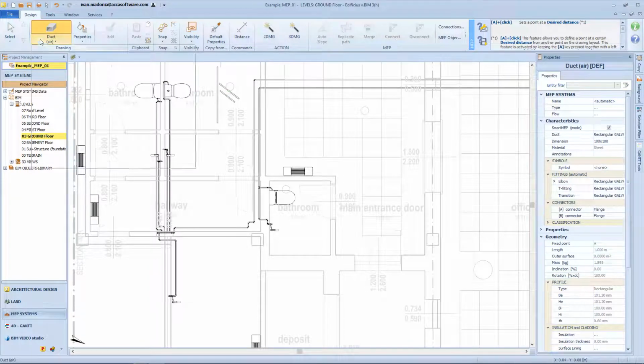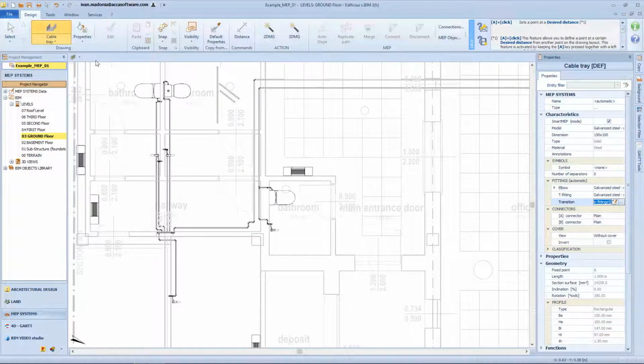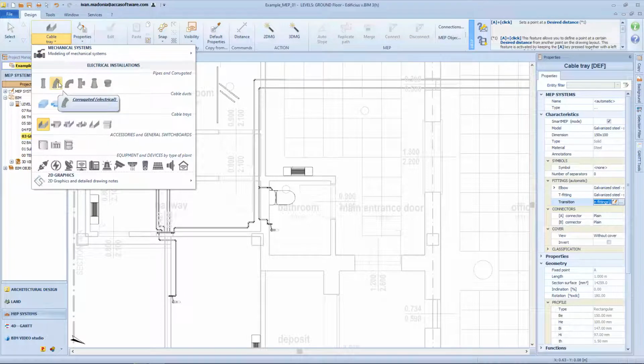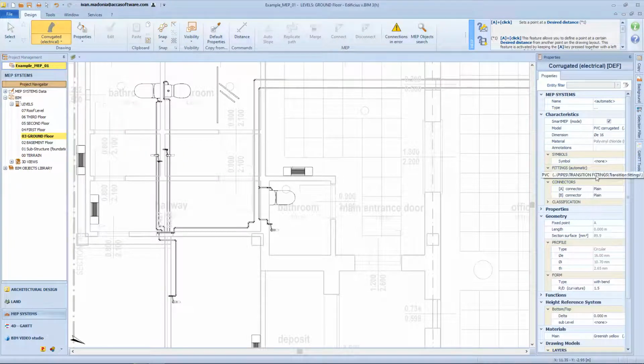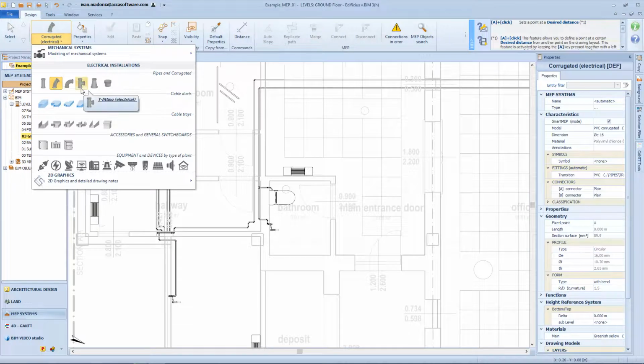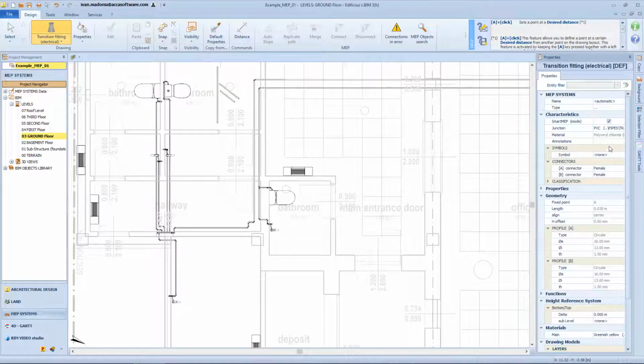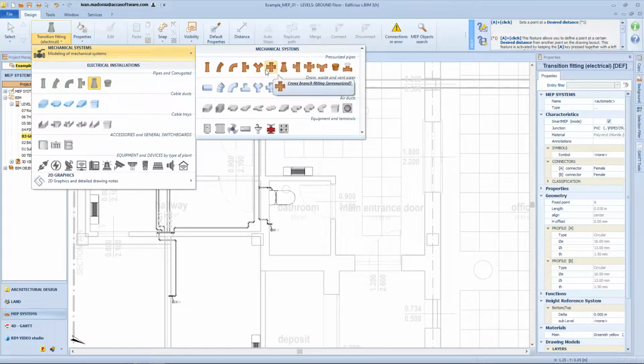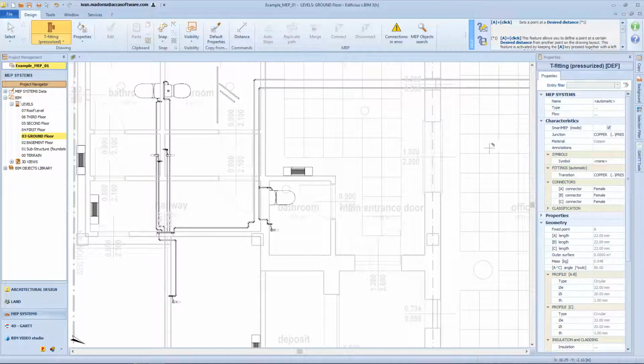With the entities of type pipe, conduit, ducts and cable trays, the curve, the T-connection and the transition fitting joint can be created. With the flexible, corrugated and all other fittings, you can only realize the transition. The same fittings can also be activated from the drawing menu, with a few differences in modeling mode compared to automatic generation. In fact, they must be customized concerning the diameter or possibly the angle between the connections before being inserted. On the contrary, automatic fittings are created directly by the program based on the connected entities, from which they acquire the profile dimensions and the angle between the connections if any.